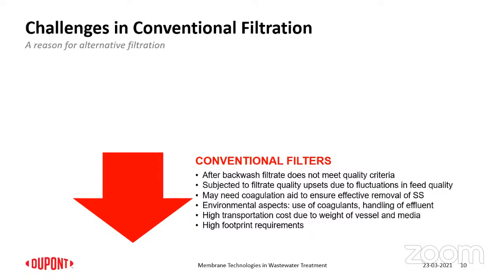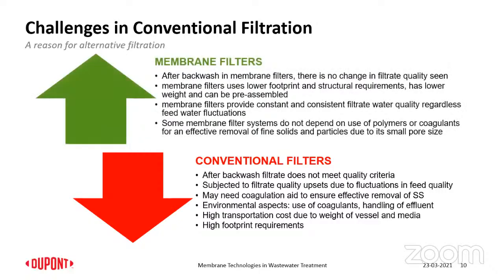On the flip side, the advantage that you would see with membranes is that there is no change in the filtrate quality because of the feed quality, and there's no expectation of change in the filtrate quality because of cleaning either. So after cleaning, it's supposed to be much better. Some filters do use coagulants, but it's not completely dependent on coagulants or pre-filtrates.